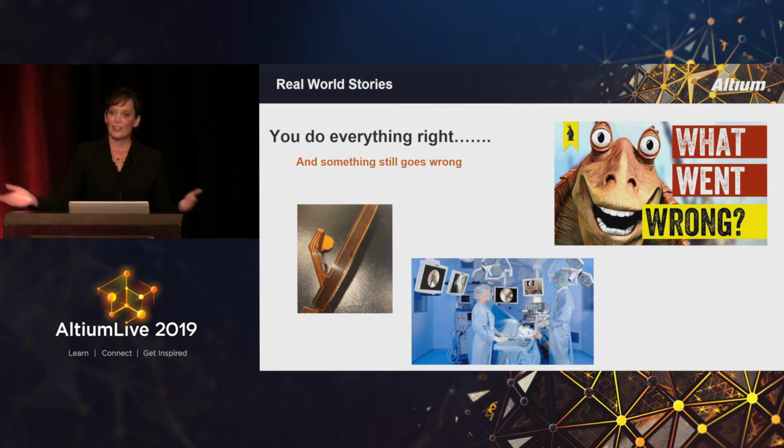So we're like, all right, we're not sure what's happening. Send some of those parts back for samples. We send them out to our labs, do all kinds of research. But again, the communication that we've opened up over that couple years was really helping us to speed this process along. At the end of the day, found out that it was measling in the polyimide material, which is fairly common, does happen. IPC addresses it, doesn't violate the IPC spec in any way. So, the board was built to print.